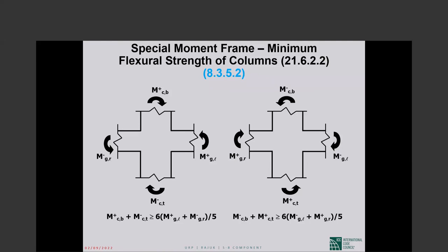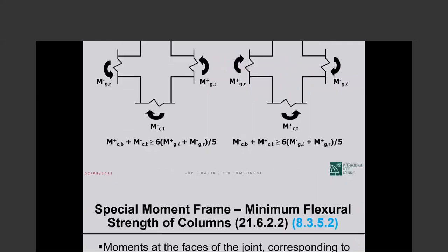That is because beams are easier to repair than columns are. Columns are extremely difficult and expensive to repair. So we want the columns to remain elastic far into the earthquake excitation. If inelastic deformations need to develop, they should develop in the beams.